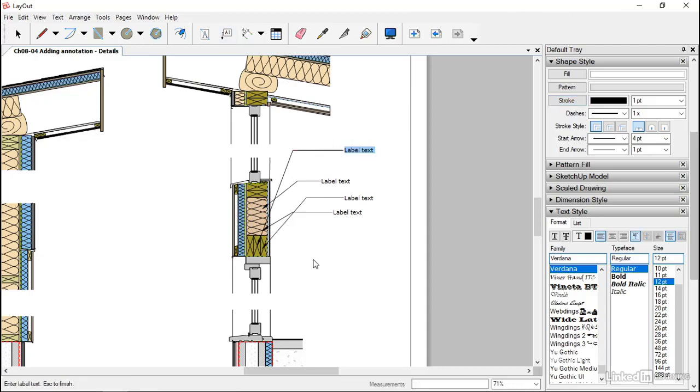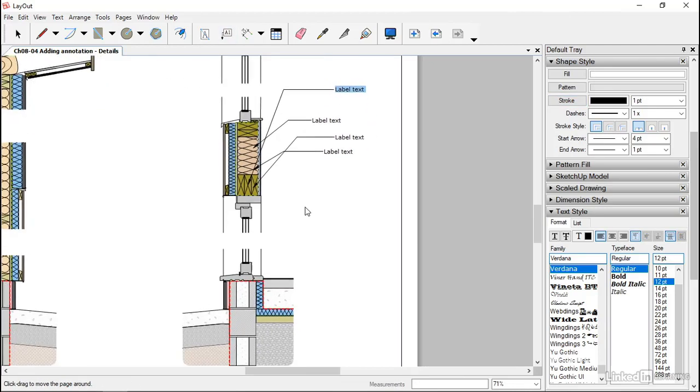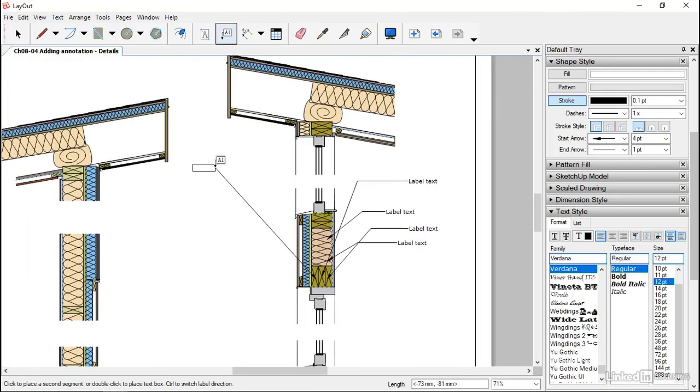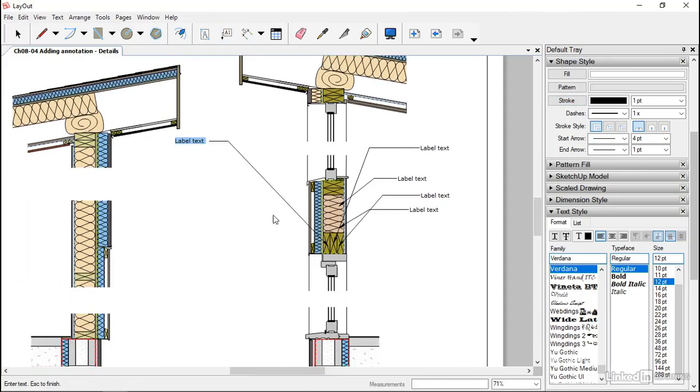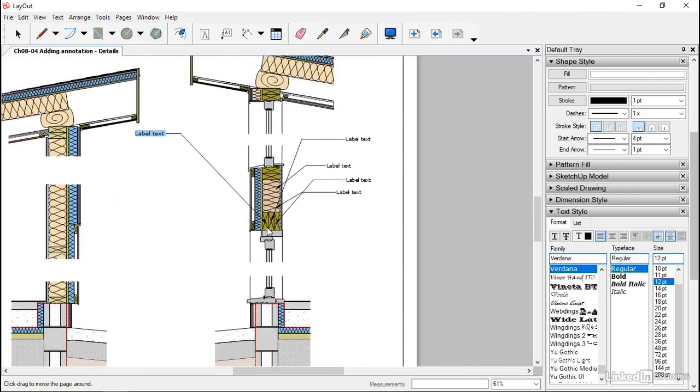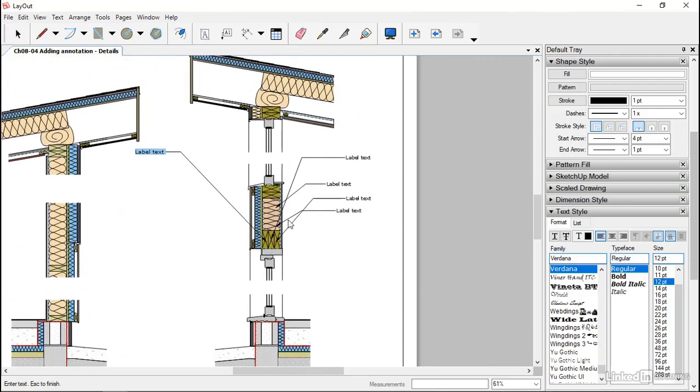Okay, now you might think, well, I would never do that, but I see this all the time. People have just decided there's a space over there that needs a bit of information, or there's a space up here that I can put something. And so before you know it, the drawing is starting to look like a complete and utter mess. Okay, so bear that in mind. No unnecessary dimensions, and try to think as carefully as possible where you put your annotation.